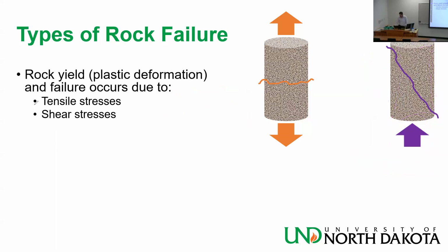So this is how you find tau. You need to calculate tau, and that depends on two stresses, right? Compare it with sigma n, the normal stress holding the rock together at 90 degrees to the fault. And if your tau is big enough to beat the normal stress, then you have slippage. Okay, you have failure.